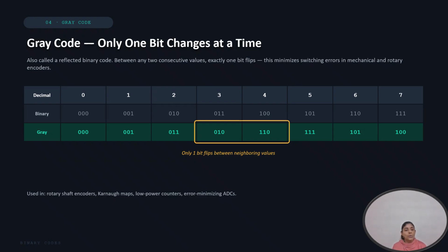Check over this table. In the first row, I have given the decimal values 0, 1, 2, 3, 4, 5, 6 and 7. In the second row, I have given the binary till 7. Then what code is this? Try to recollect. Yes, exactly. It is the 4 2 1 code you have used in your octal number system. For 5, 4 plus 1 is 5, so the 4 and 1 are switched on, other values are switched off. That's why you got 101.